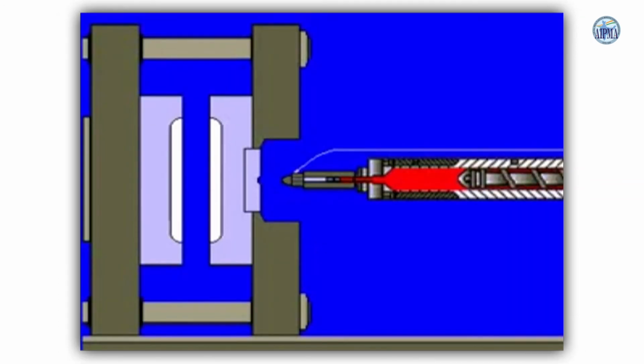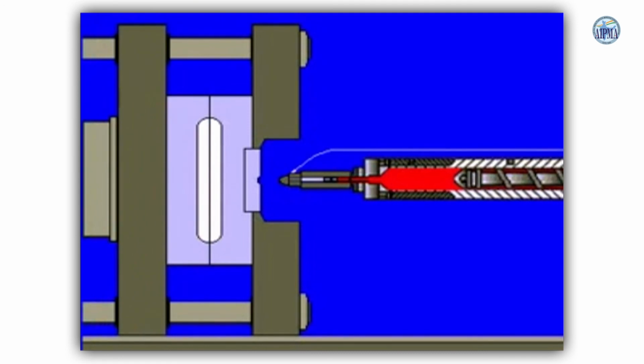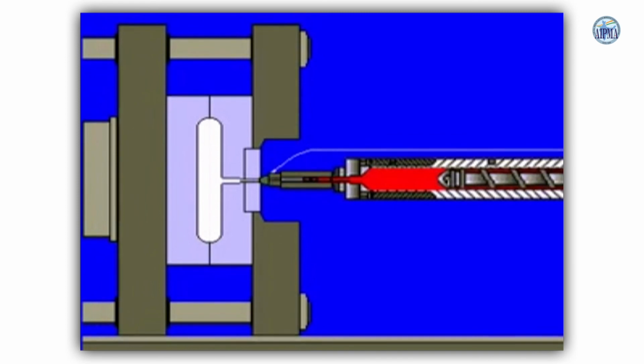Gas assist injection molding is a low pressure process that requires the injection of pressurized nitrogen gas into the interior of a mold. The gas flows through strategically placed gas channels to displace the material in the thick areas of the part by forming hollow sections.